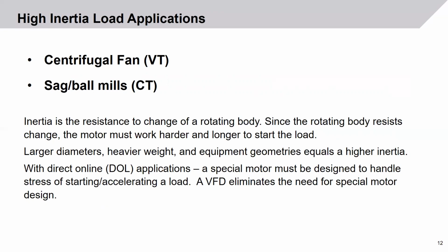But inertia is the resistance to change of a rotating body. Since the rotating body resists change, the motor must work harder and longer to start the load. Larger diameters, heavier weight, and certain geometries of the equipment equal a higher inertia. With direct online or DOL applications, a special motor must be designed to handle the stress of starting or accelerating such a load. VFDs, however, will eliminate the need for special motor designs.